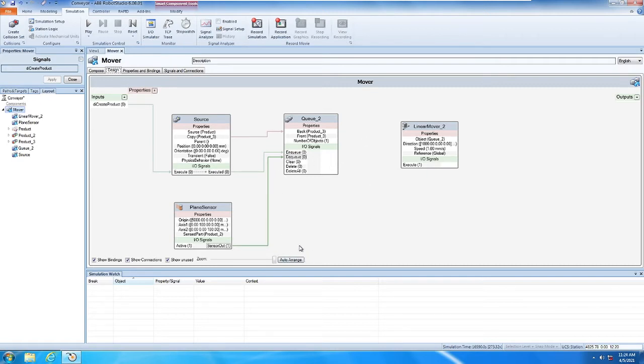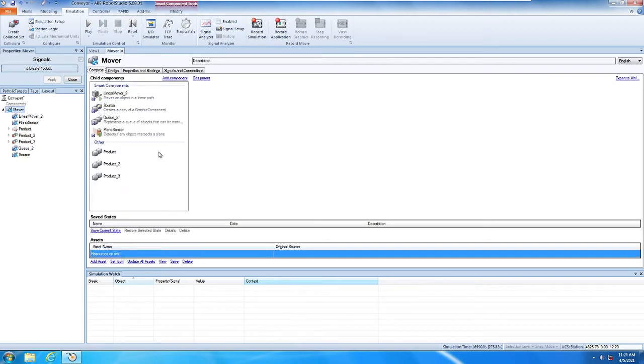So what I'm going to do is delete the DQ, the front part, and also I'm going to stop this conveyor too. Then if I stop this conveyor, the whole queue will be stopped too. Okay, let's go back to Compose, and then Add Component.